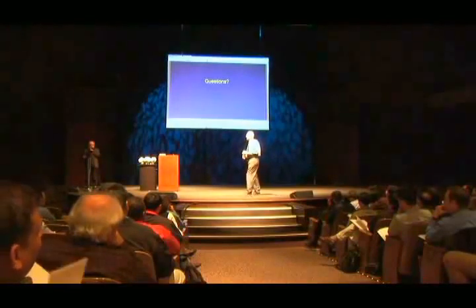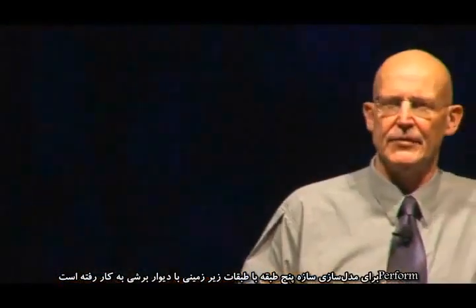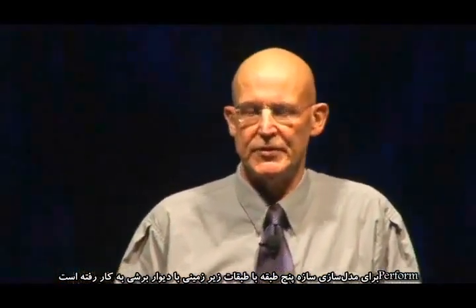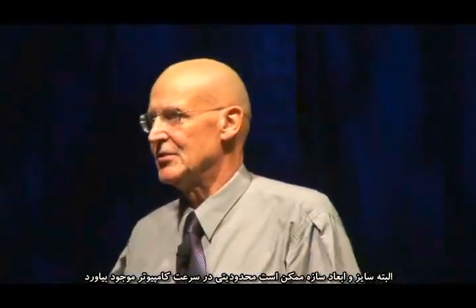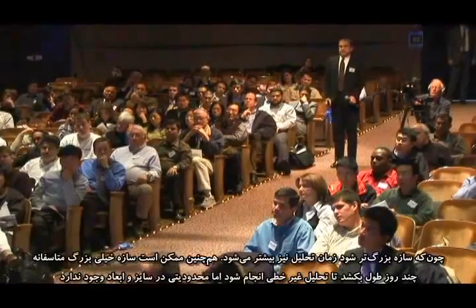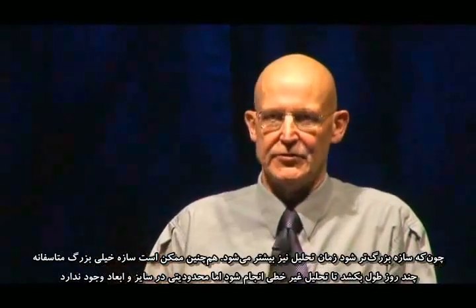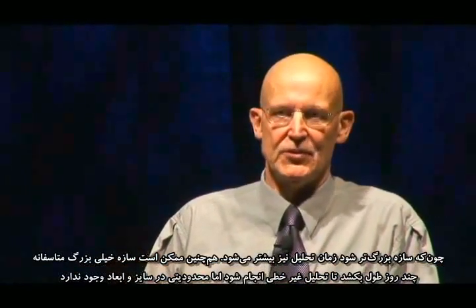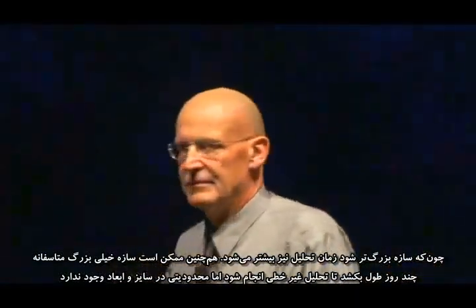Perform has been used for, I think, even a 100-story shear wall building. And that's with the current Windows operating system. When you go to Windows Vista, which has got 64-bit, it's going to be huge. The limitation isn't so much the size of the structure, it's the speed of the computer, because as the structure gets larger, the analysis time gets larger also, and for very, very large structures it can be a matter of days, unfortunately, for a nonlinear dynamic analysis. But there's really no limit on the size.